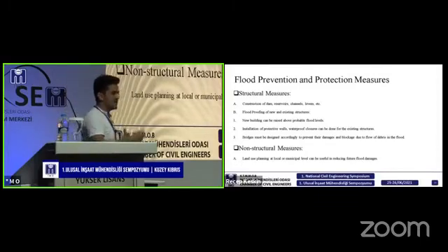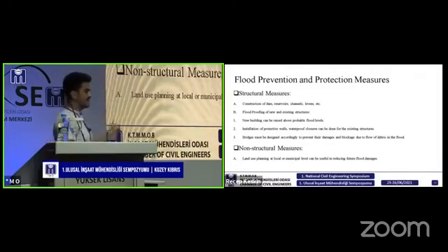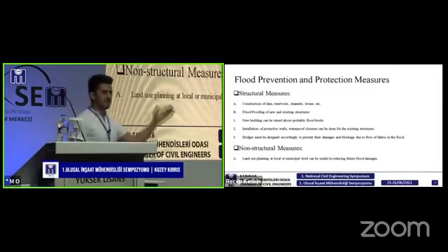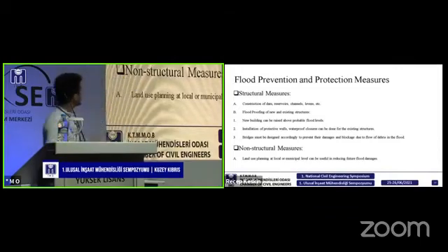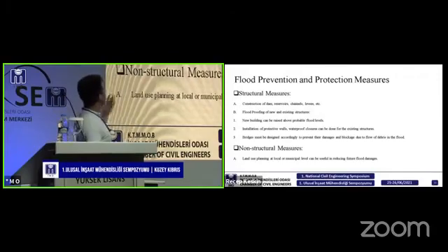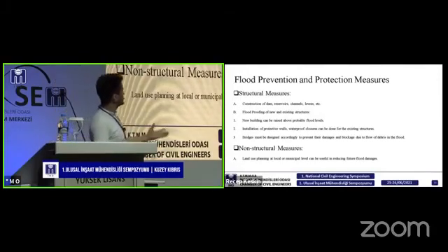How can we implement the flood protection measures? For new buildings that are being developed, we can propose that they increase the level of their entries to above the flood level. We can recommend the installation of flood protective walls, waterproof closures, and bridges.